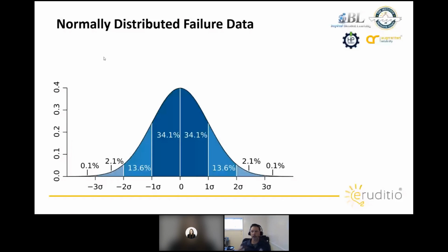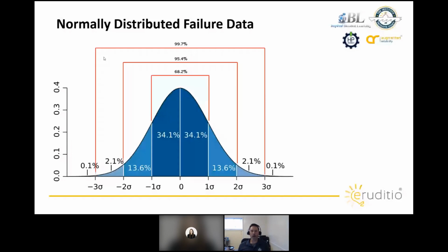Therefore, we might be changing out components too early or getting way too close to failure or potentially running into a functional failure standpoint. So we want to inspect a variety of times. So if we can inspect 6 times over that P to F interval, we've got a 99.7% chance of finding that failure before it results in a functional failure. So that's what we're really aiming for.